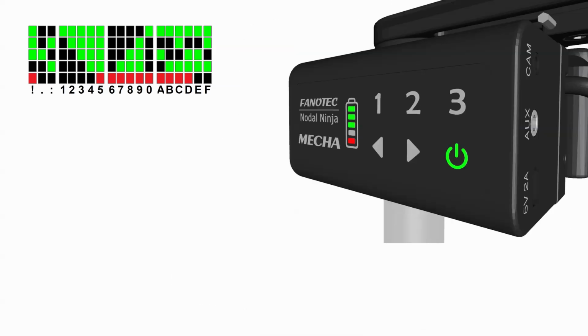If you enter the code 321 to retrieve the last octet of the IP address, and receive 3 exclamation marks instead, it means the Wi-Fi is off. If the LEDs display 3A letters, it means MECHA operates in AP mode, and the IP address is 192.168.8.1. If either .0 or 0.0.0.0 is displayed, MECHA is not in AP mode and does not have an IP address assigned. It is in STA mode but is not connected to a network.